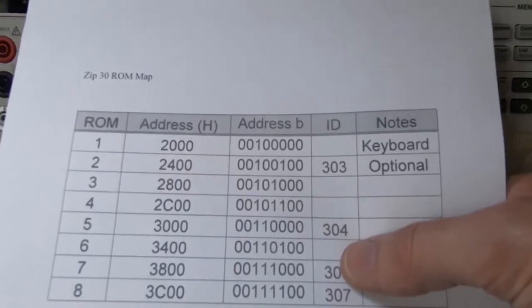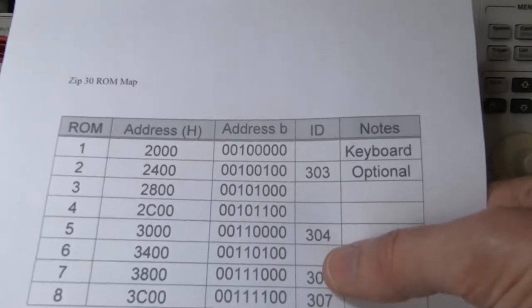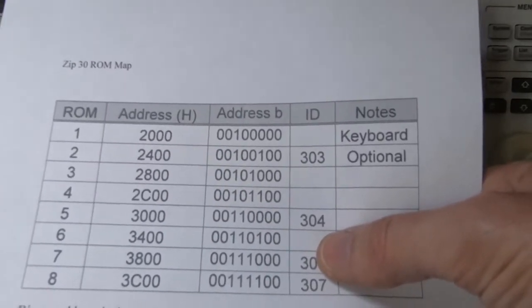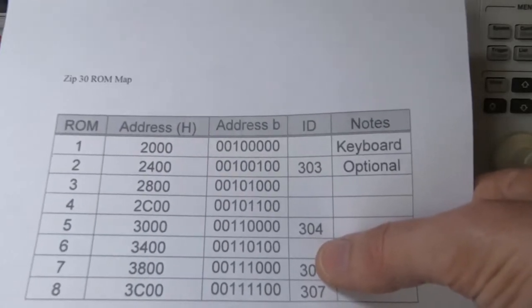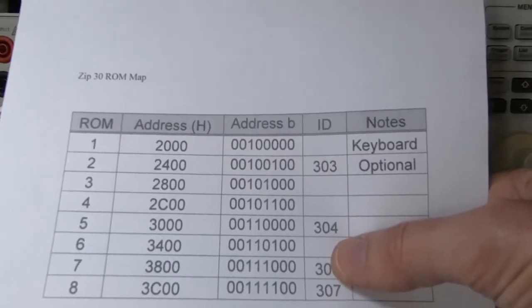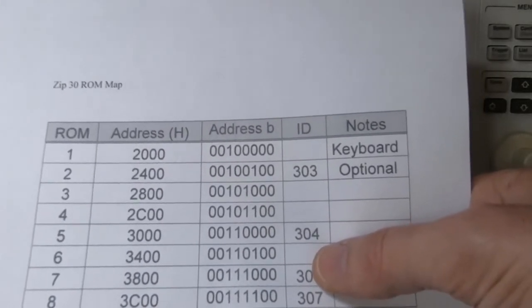If you then capture the instruction at that particular address, you can look into the ROM and see where it is within the ROM. You can then work out essentially where that ROM fits within the address space and what its start address would be.